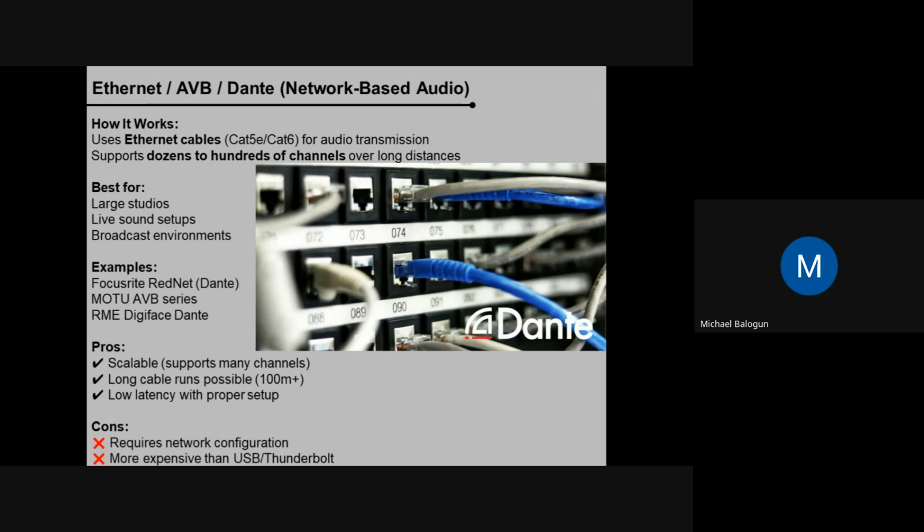Once you have a system, sometimes we will record up, record down, record on stage, because we also have a module there too that we just plug in. But I must warn, it has a switch. If you want to enjoy that, you need to use a gigabit switch because of the data. So a gigabit switch, not just a regular switch. One of the functions of the switch is that once you get your signal out of the Dante card, you can plug it into your system directly.